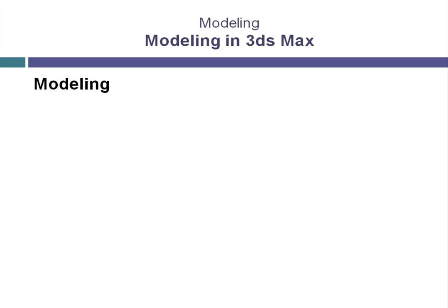Once we've pre-planned our project and got client sign-off, we need to move into the content creation stage, beginning with modeling our 3D scenes. We'll start to open 3ds Max and create the models we'll need for the first panel of our storyboard. We'll do this by first working with 2D shapes, an efficient and effective method of creating the basis for your 3D models.